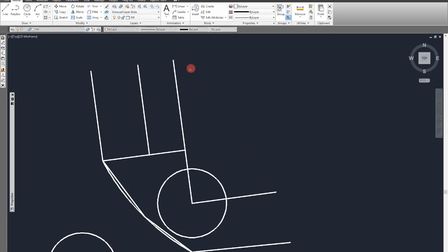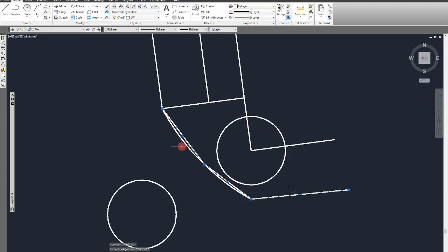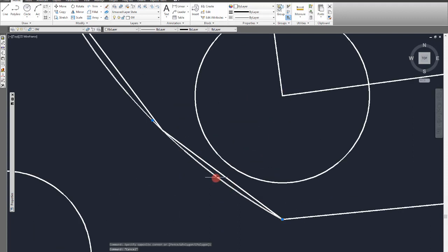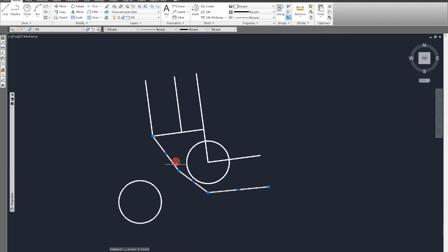Mirror is a slightly more advanced command, but it is also often used. It allows us to mirror a certain element based on a certain line. That will be a mirror line. That means the element will be exactly the same, just with a different direction based on the mirror line. Now I will demonstrate it. Let's say we want to mirror this polyline. Now I will delete this arc here. Let's say we want to mirror this polyline alongside this mirror line.